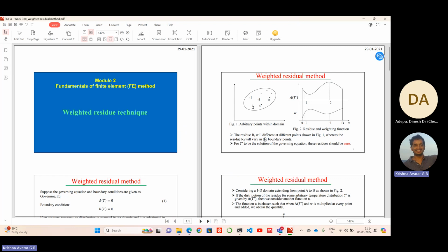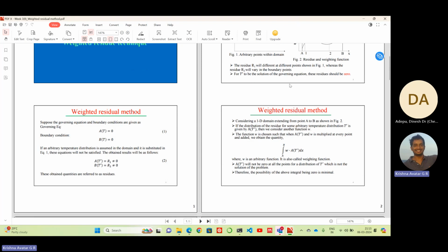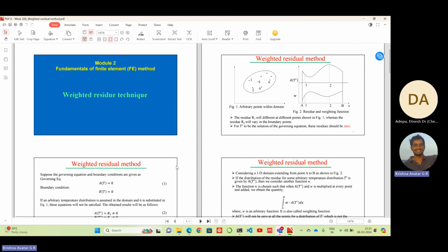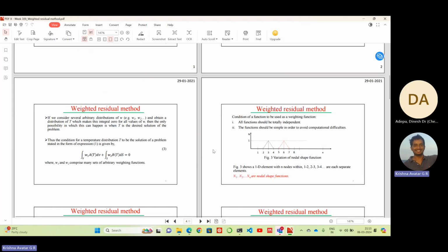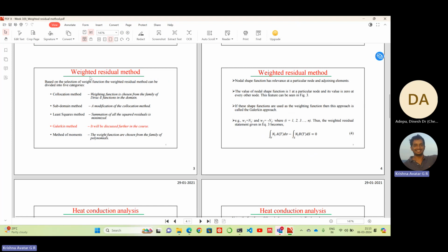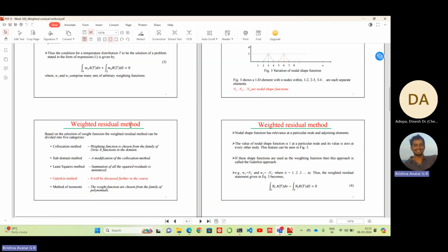Now, that's interesting. We are trying to discuss heat source models today, because that's what will be relevant throughout the lecture series after that. I had also talked about the weighted residual method that day using a simpler way, I think. Weighted residual is we just weight all the residuals such that the integration becomes 0. The same statement has been said in a much more complex manner.